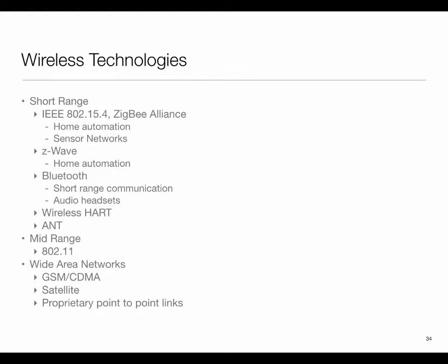But then I could perhaps use one of these, like a Bluetooth LE, or there are even companies which sell so-called wake-up radios. And the idea is that your system can go to sleep, and then I need to wake the other node up. So there is a tiny little radio on that other one which is just listening for a hello message, and you send that out, and this node then wakes up, and then both switch to a higher capability radio. So just the same analogies that we talked about, big.LITTLE, there is a big.LITTLE counterpart in radio also, where you mix and match 802.11 with one of these, or perhaps even the specialized wake-up radios.